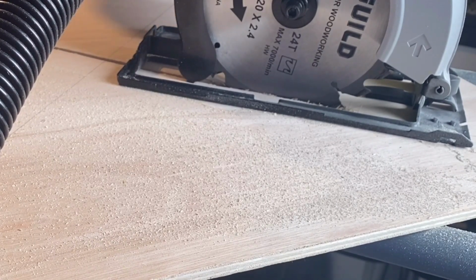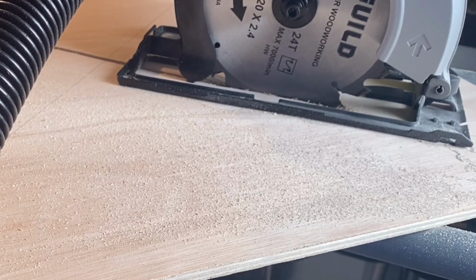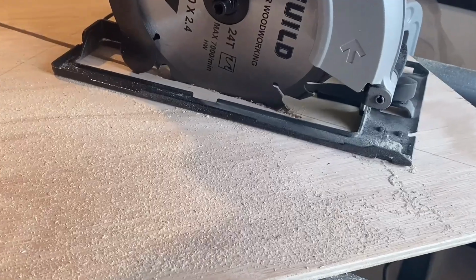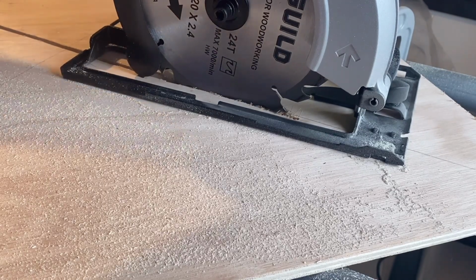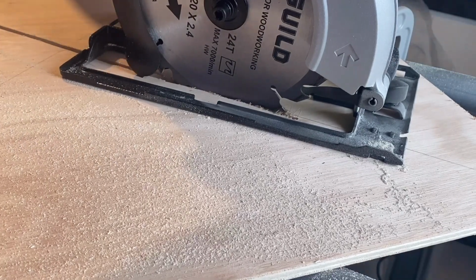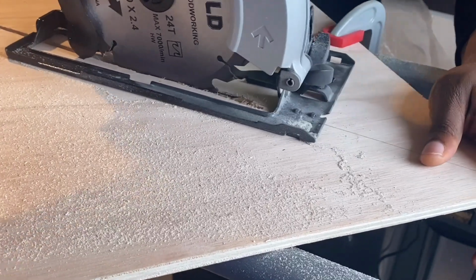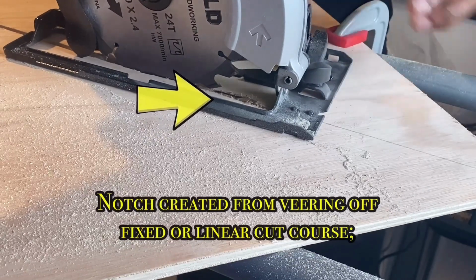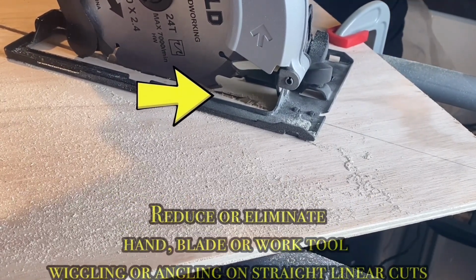At this stage, I have ascertained that the blade isn't angled and it's free spinning, so I'll proceed to finish off the cut, as I am pretty confident that the saw blade would not be latching or cutting into the sandwiched sides of the hardwood plywood. Just make sure there's enough room and it's not picking on the sides of the plywood before you proceed to finish off your cut through the cut line.